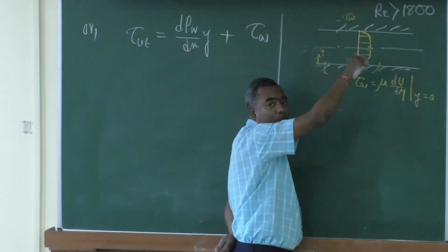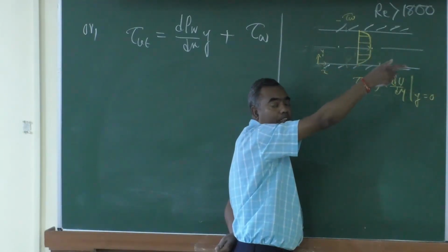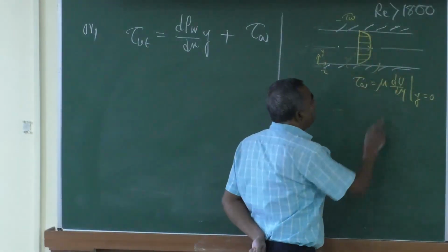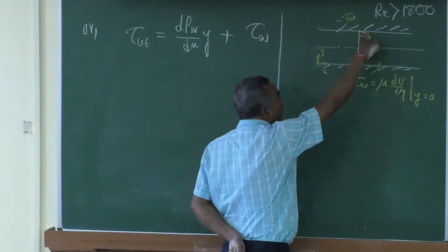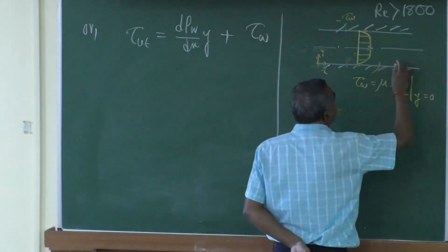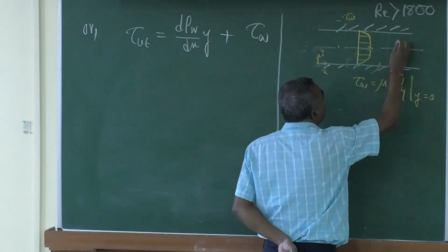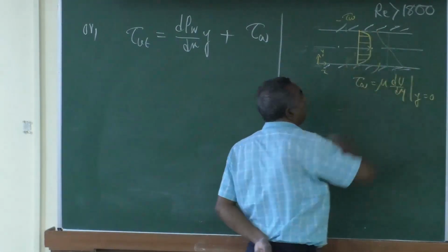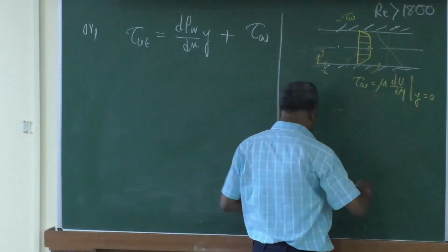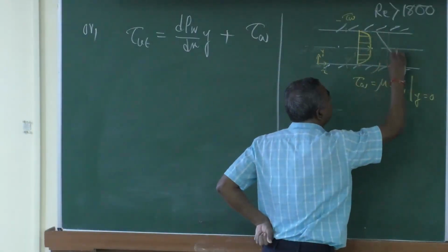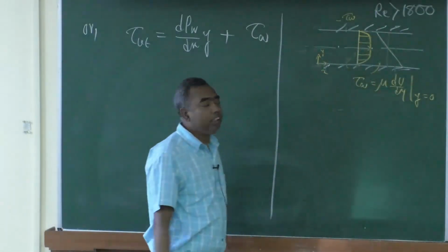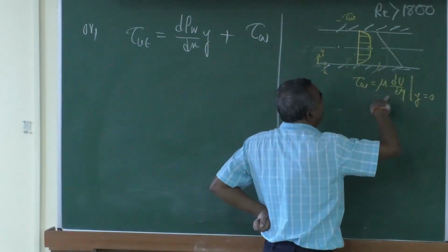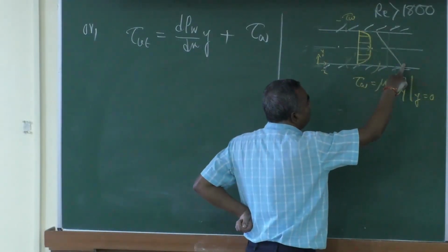Okay. So, delta u divided by delta y, which is nothing but du/dy, is going to be negative for this part. That means the viscous stress is asymmetric about this. If you plot the viscous stress, it is asymmetric, with the maximum value somewhere here, then it will be something like that. It may not be linear, but anyway something like that you will get. This viscous stress is asymmetric about the central line, positive in the lower half, negative in the upper half.